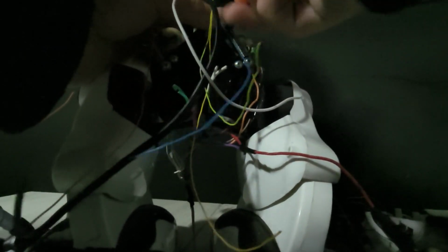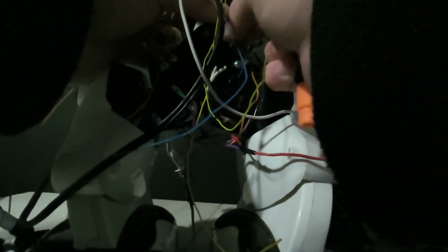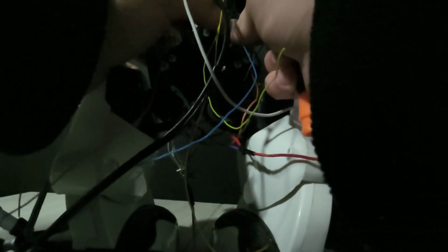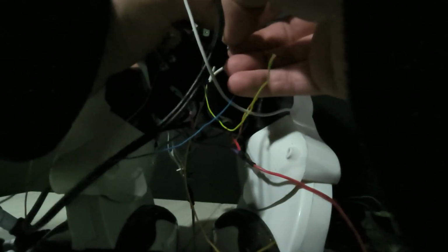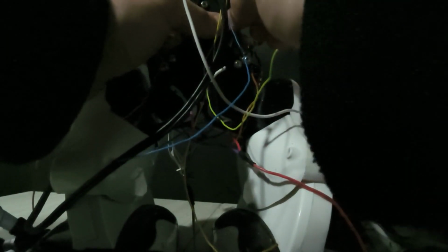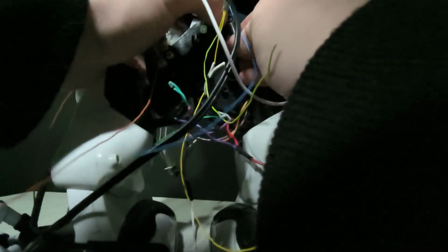You'll also need 2 wires coming out of the back that connect to the batteries as well as the 5 volt board, and that goes to the motor controllers so that you can later take apart the robot. And we'll leave the I2C alone for right now because we need to build the head of the robot, which also ties into the I2C system. But you should have 2 pairs of I2C wires coming out of the back of your robot at this point.